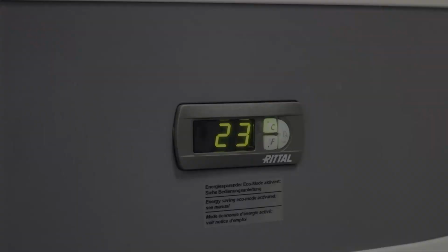One of the features on our Blue E air conditioners is called filter monitoring. What this will allow you to do is set up a signal so that when the airflow starts to become restricted due to contamination or a filter that is becoming clogged, it will experience a temperature rise, and that temperature rise will then signal that you need to replace the filter. So I'm going to walk you through how to set this up on your Blue E air conditioner from Rittal.